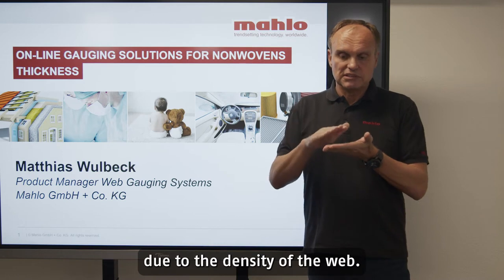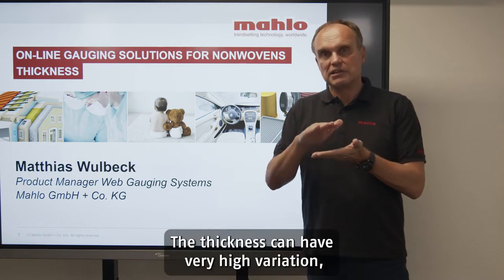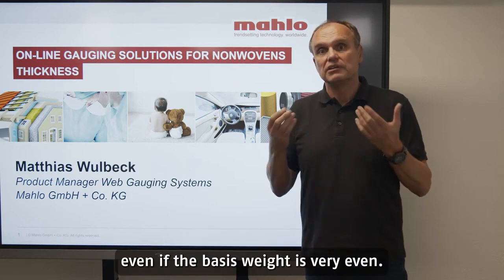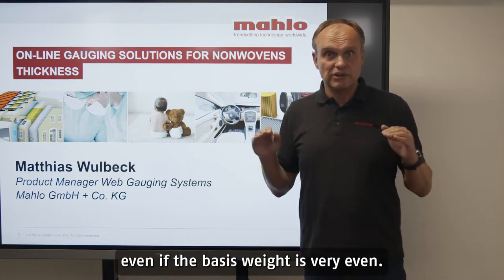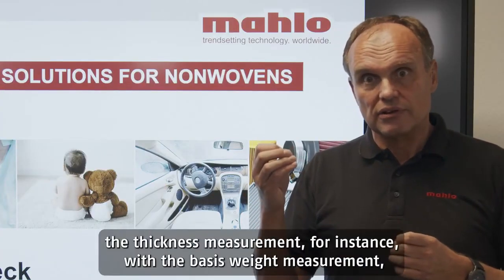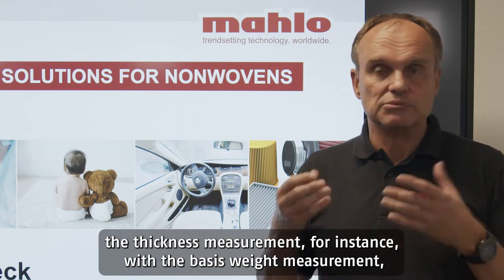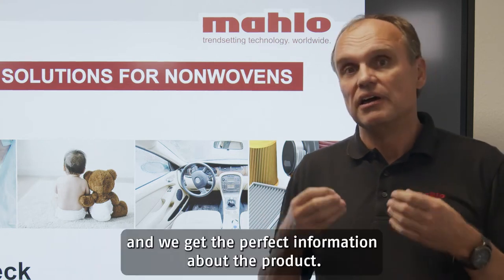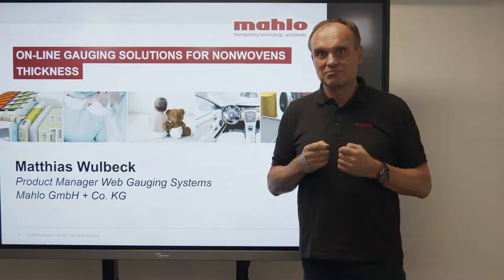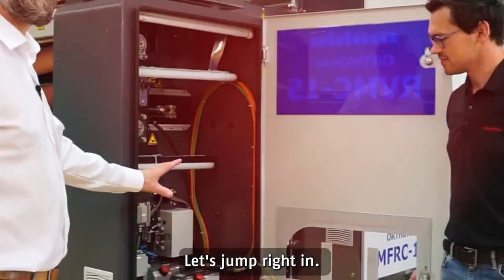Due to the density of the web, the thickness can have very high variation even if the basis weight is very even. So we combine the thickness measurement, for instance, with the basis weight measurement, and we get the perfect information about the product. Let's jump right in.